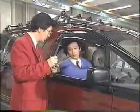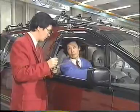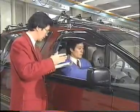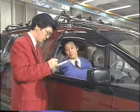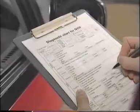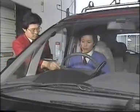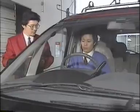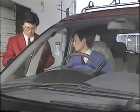An important thing in troubleshooting is to forget all your preconceptions about vibration and to listen to and analyze the customer's complaint accurately and objectively. A diagnostic chart may be helpful. If possible, you should also get into the car with the customer, test drive the car, and confirm the problem in some detail.